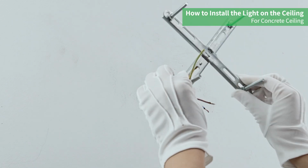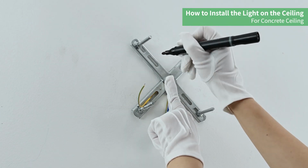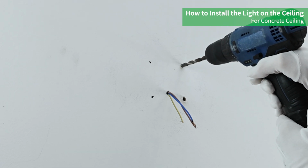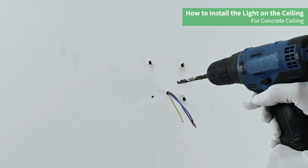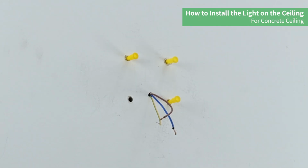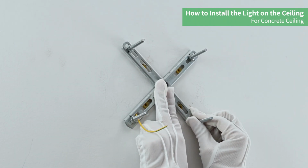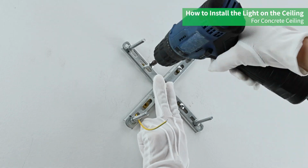For concrete ceilings, place the cross bracket at the desired installation location and mark the positions for the screw holes with a marker. Use a drill to first drill holes at the marked positions. Drill holes 2 to 5 mm deeper than the length of the expansion bolts, with a diameter that matches the bolts. Insert plastic expansion bolts into the holes to secure them. Remove debris and dust from the holes. Use an electric screwdriver to screw pointed screws into the holes, securing the cross bracket.